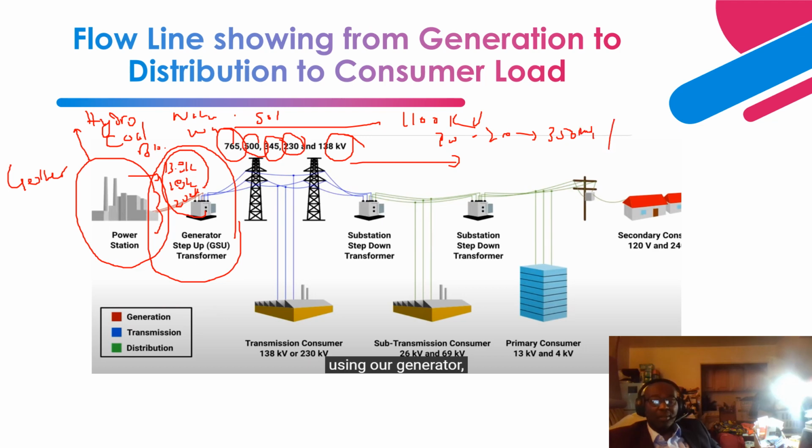Usually there is a break-even point, more than 400 kilometers. You don't want to go beyond that because for AC transmission you experience significant reactive power losses and resistive losses. At that time, you need a substation, and this is where the step-down substation comes into play.